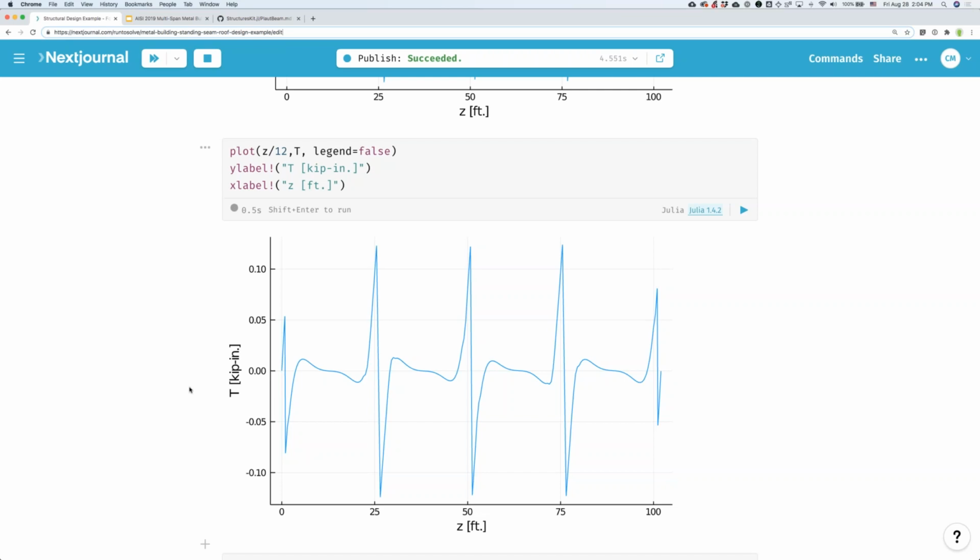because we have assumed that the lateral clip stiffness is half, so we're assuming the roof is restraining the purlin less, and so more torsion builds in the purlin, and less of the eccentricity effect goes into the roof and more goes into the purlin. This is another really key point that becomes clearly visible here: changing these clip stiffnesses or clip spacings and types affects how much of the torsion from the load eccentricity goes into the roof and how much goes into the purlin.